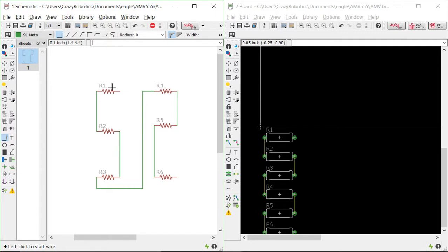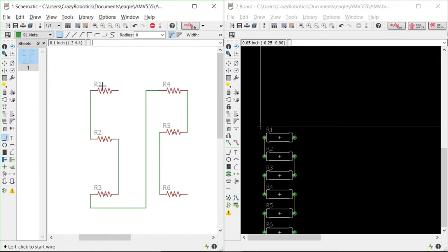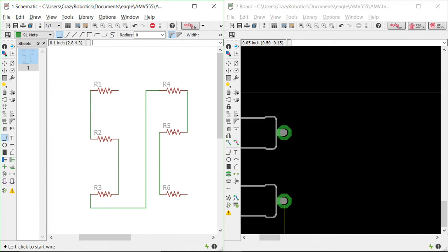So it is very important to note here that in R1 and R6 one of the terminals is not connected. So what would happen? You would imagine that you would be generating the schematic file and converting that into a layout where you are expecting some output terminals which can either be soldered with a wire or some external component.